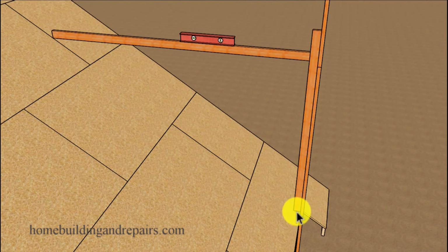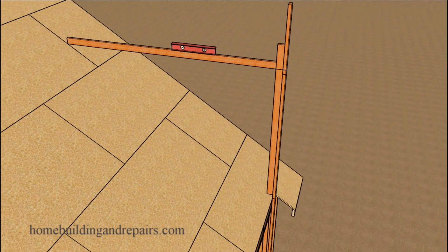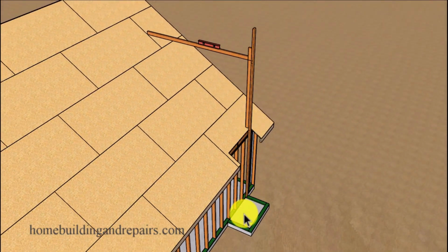It's going to be the measurement off of the top of the roof sheathing, where the farthest point of the chimney on this side is going to intersect with the roof sheathing. Not always going to be this point right here. So let's go ahead and put our mark in there. And this will make a little more sense when I provide you with a final example of what the chimney is going to look like.